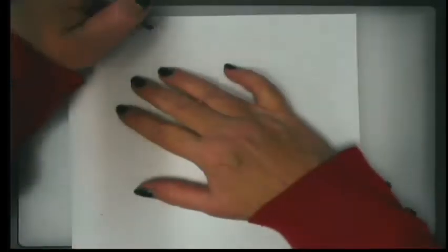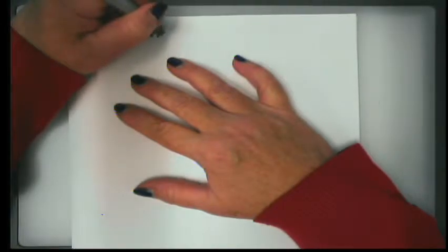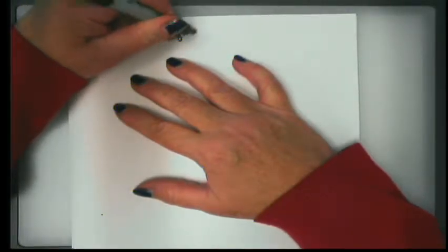So, in terms of analysis, what we are doing is we're acknowledging that if we have a simply supported beam, the load on the beam is not going to be the same everywhere, that the moment is going to be different from one slice to the next, and that the V, or the shear, is possibly going to be different from one slice to the next as well.